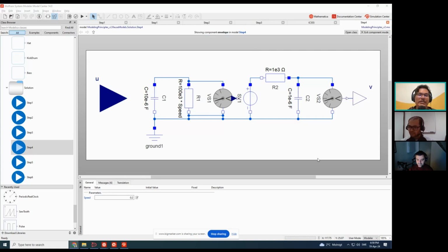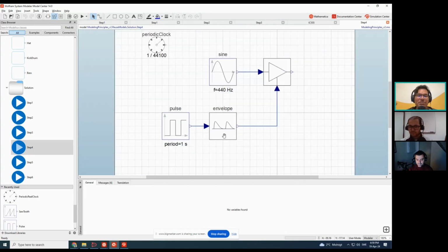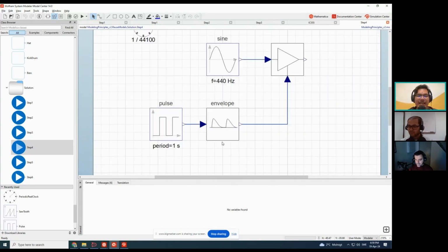An envelope is used for that, in order to generate a sound that is high in the beginning, and then we can control the amplitude. We use that signal to control the amplitude and make it decay, as a natural sound. That's what we are seeing here. It goes up and then it decays, and that is what this component is trying to create.